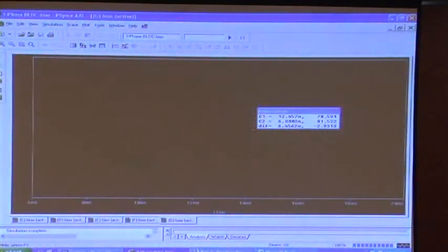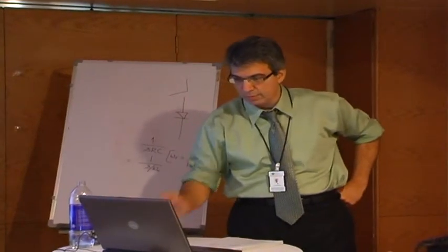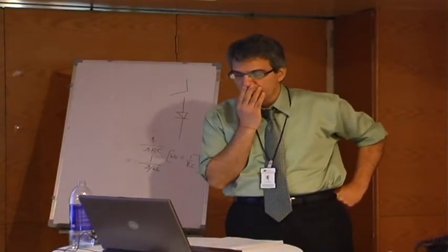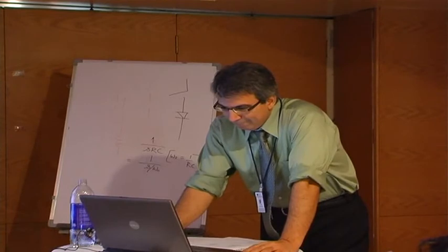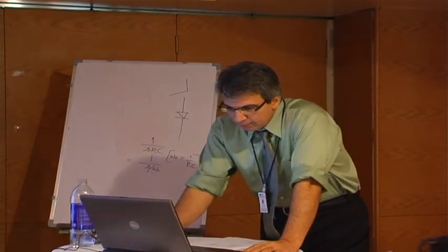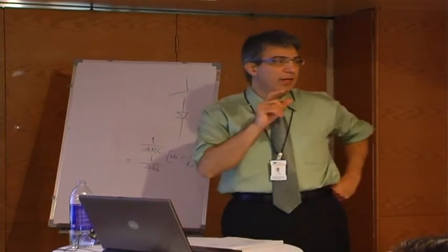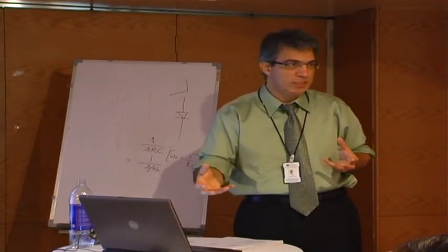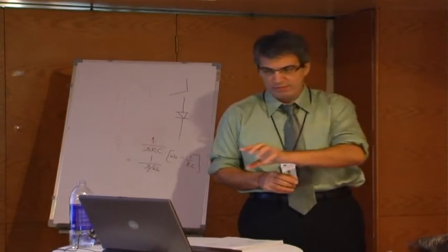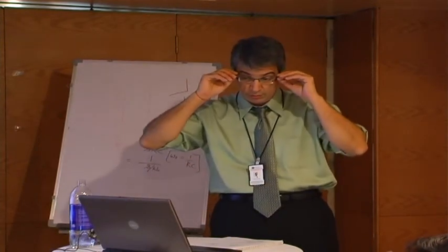And anything else we want to see on this? Do we want to change the reference? This was reference 2, and we can definitely change it and see what happens. You can see output power. Now the way to do that, you can also define one function within SPICE which will multiply voltages and currents and give you power output. We haven't done that in this one, but we have another demonstration where we show that.